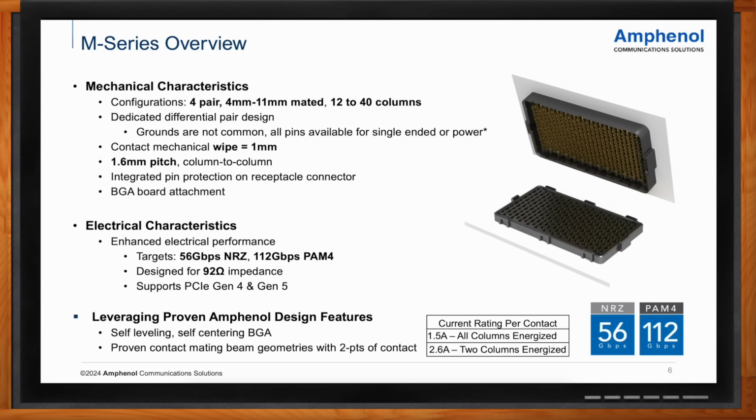Again, like MEGArray, it's tooled in a variety of stack heights because we are supporting customer applications where they need that variety. So 4 millimeters on the low end, up to 11 millimeters at the tallest stack height tooled today. The design will go up to 14 or 15 millimeters in the future if a customer should need that. In the case of M series, typically because it's a diff pair connector, we're looking at the number of diff pairs in the connectors or the number of columns. And when we say a column here, each row or column has 4 diff pair within the pin count.